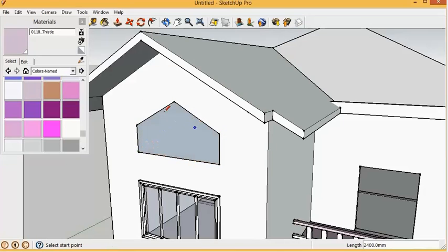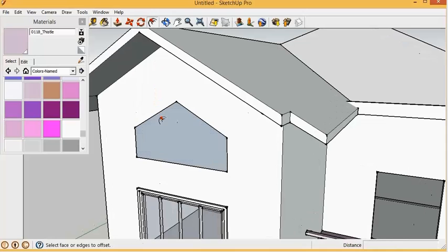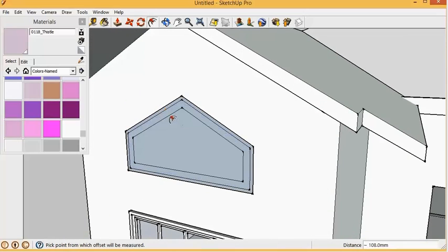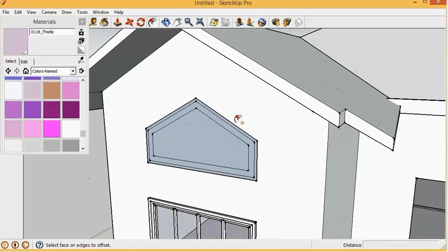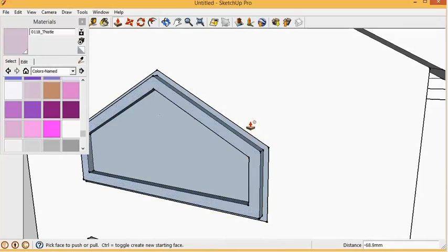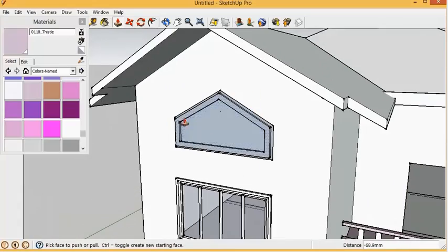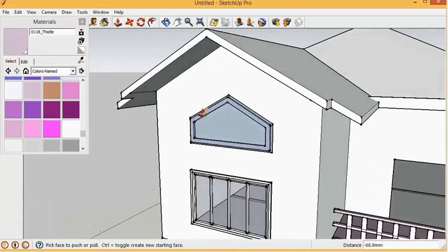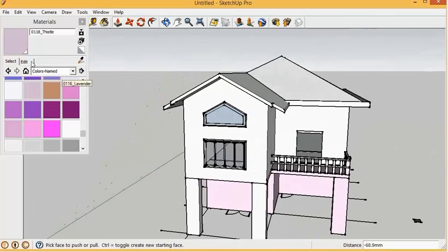So you can find the protractor tool here, or if you want, you can go into Tools, Protractor. And as you can see, it looks very similar to the rotate tool, in that it creates this protractor-like interface. Now, if you want to measure an angle, all you have to do is hover over what you want to measure.